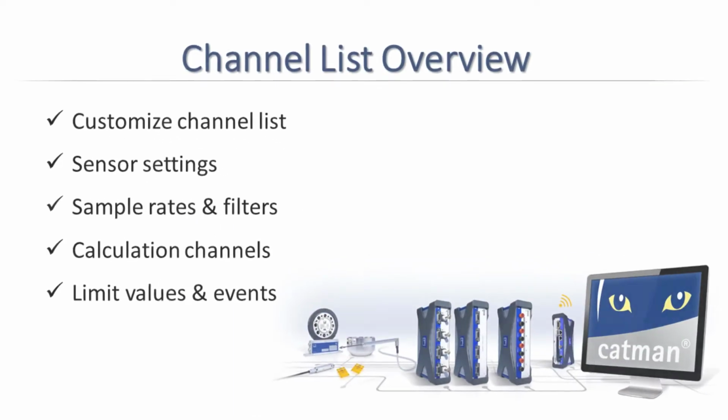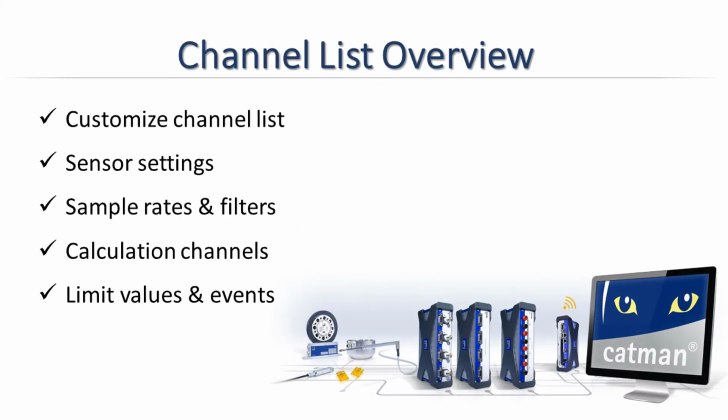This video will give you a quick overview of the channel list tab in Catman. We will show you how to visualize in the channel list, how to modify channels, and how to prepare sensors for measurement. We also show you how to assign sensor settings and the desired sample rates and filters to the measuring channels.